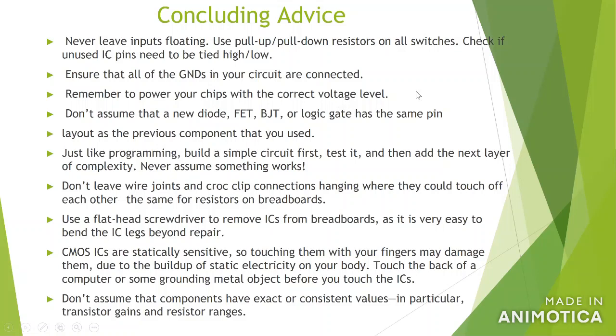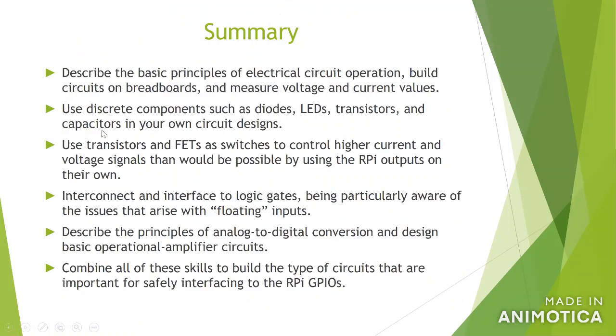Don't assume that a new diode, FET, BJT, or logic gate has the same pin layout as the previous component that you used. You have to read their manual to know what pins it has.